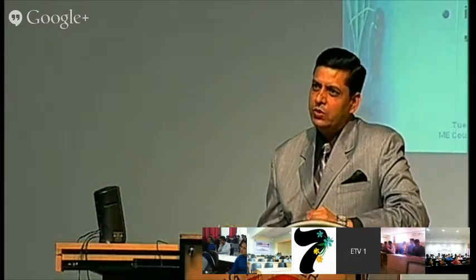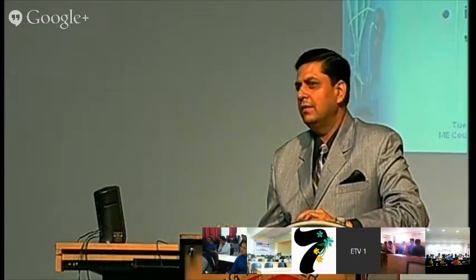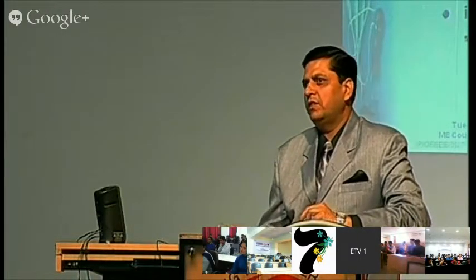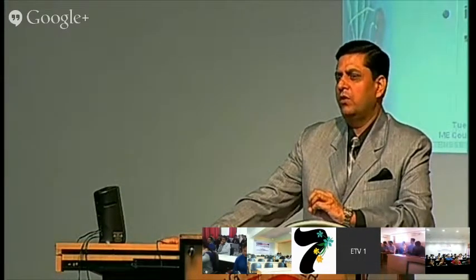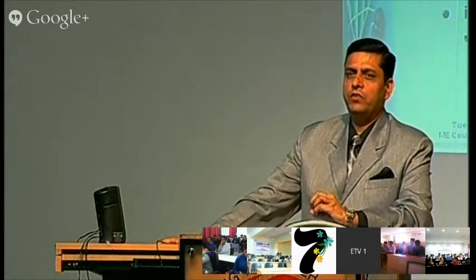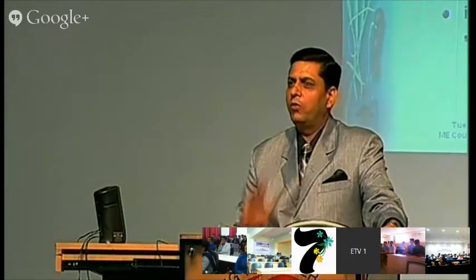In addition, these editors also show connectivity information between modules, in the form of rat's nests, meaning straight wires, and those wires are not routed wires. Those wires give you information about the connection of your different IOs with your circuit, and they are not completely routed. These rat's nests will be in the form of straight lines. These are not final routed tracks.